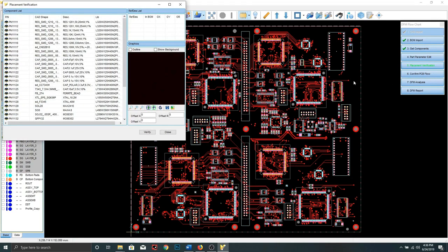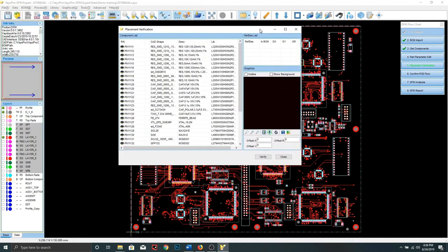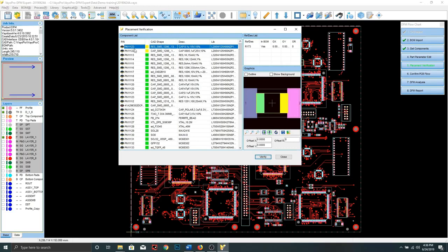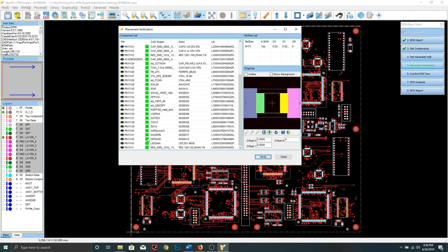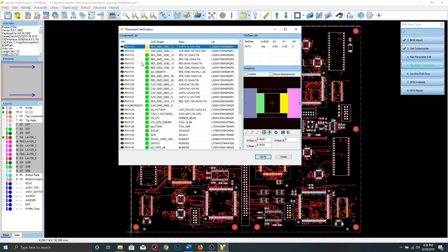In this step, we shall perform the virtual assembly and make sure each component is assembled with correct rotation and position. In just one click, DFM Expert will automatically correct the part's mount, rotation, and position. Here, DFM Expert also captures 2 obvious package mismatch problems. Let's save them to the final report. Using this function, we can find out major assembly mismatches and meet prototyping DFMDFA analysis needs.